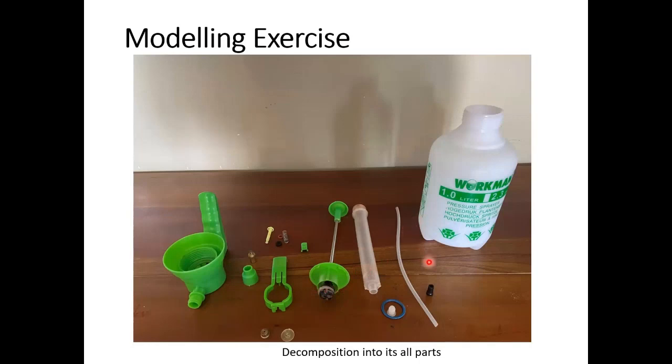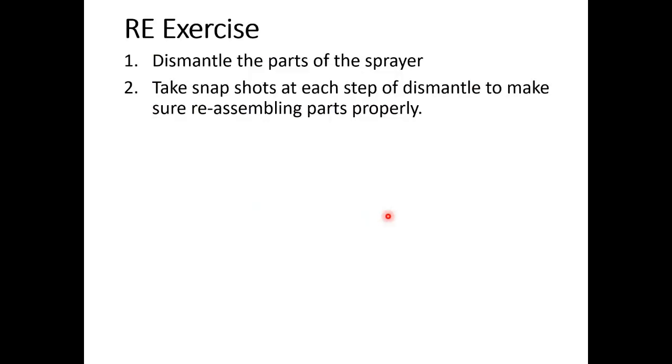And then after taking all these parts out and doing your measurements and all these investigations, we expect you to put all these parts together again and reassemble the product. Therefore, it is very important and advisable for you to take photographs at each step when you are taking parts out. So take photographs in series as each and every part is taken out. So when it comes to reassembling the parts, if you're not sure of how they are going to be put together, then you could refer to these photographs and do the reassembling.